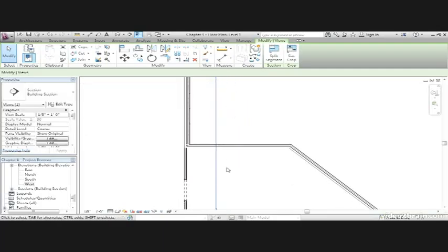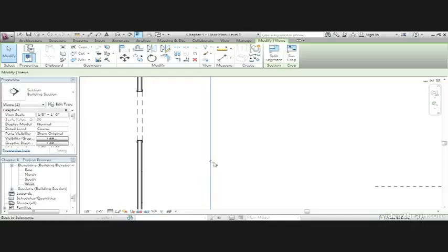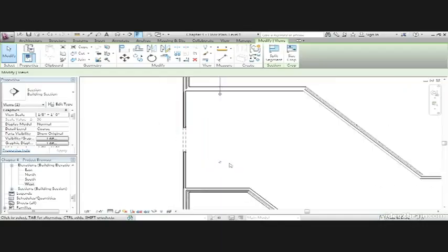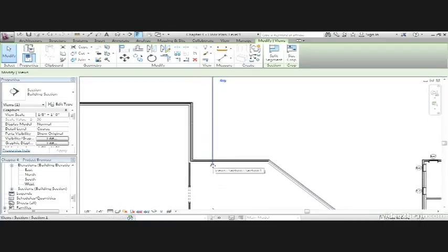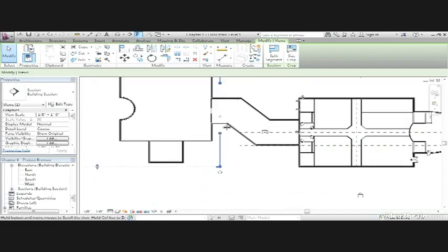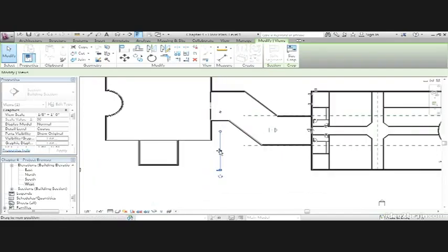Let's scroll down the section a little more until we arrive at the middle. You see this little Gap in Segments button. What this does is it allows you to chop out the section so it's not in the way or crowding up your model. I'm going to move this little grip up to about here. I'm going to move my little grip down to about here.